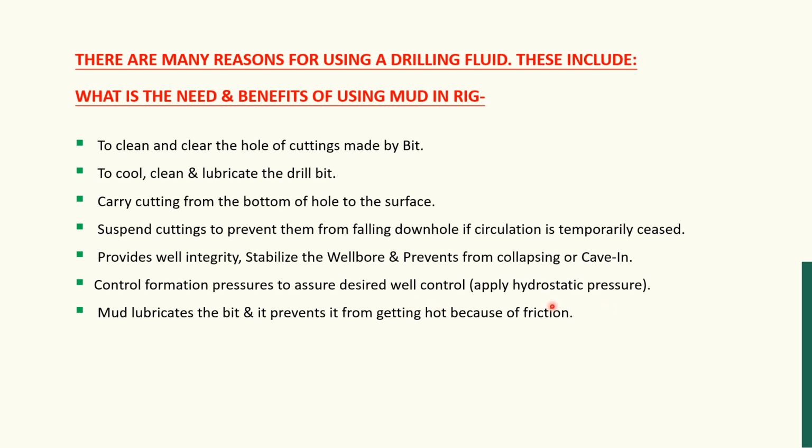Apply hydrostatic pressure. There are two well control elements in the rig. Number one is the hydrostatic pressure, and the second one is the BOP, which prevents the blowout or controls the kick. The drilling mud is the important factor that creates the hydrostatic pressure, and hydrostatic pressure controls the formation pressure. So it is very important.